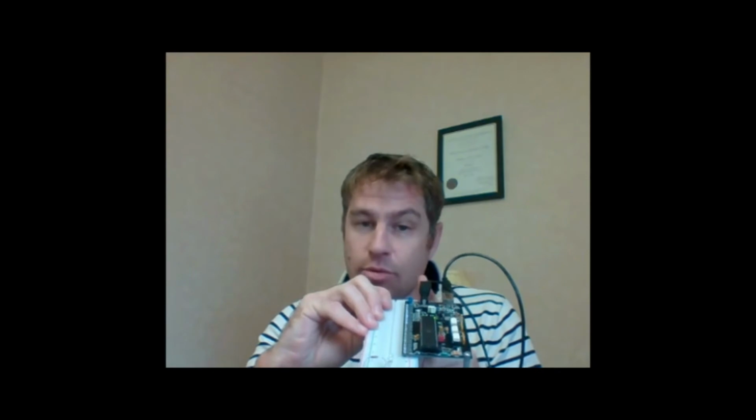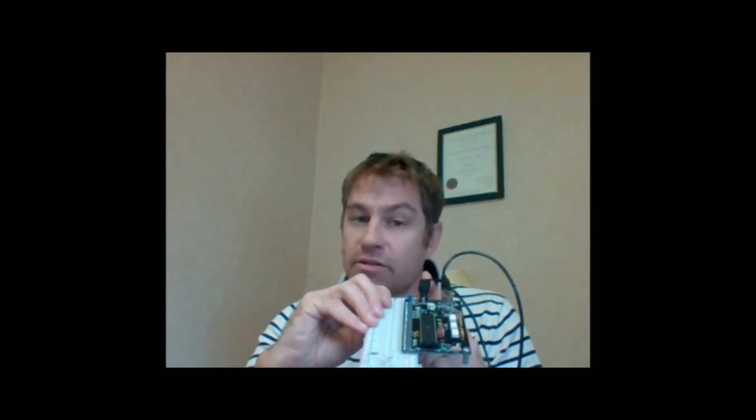If I put a 5 volt, so the embedded processor is nominally operating, the GPIOs are operating at 5 volt, even though we're supplying the input of the voltage regulator with 7.5 volts. Here at the headers, I'm not supposed to give it more than 5. And if you give it more than 5, there's a good chance that you're going to fry your circuit. So make sure that all the signals that come into your headers never go above 5 volts. So a 5 volt is a logic 1 and a 0 volt is a logic 0.